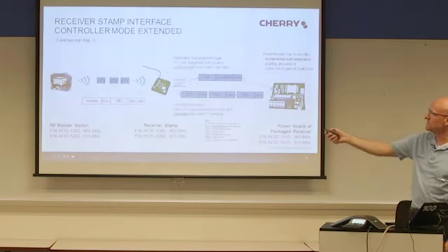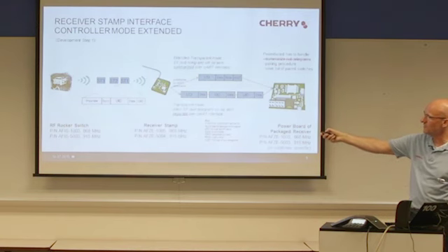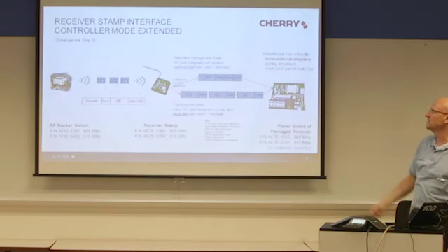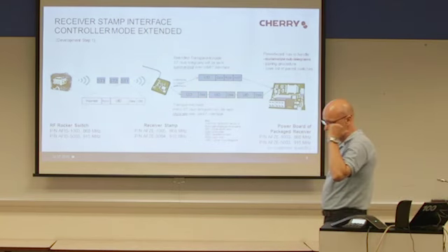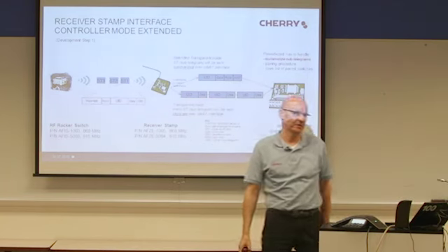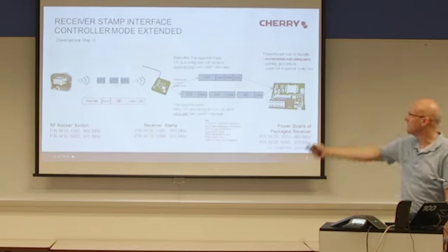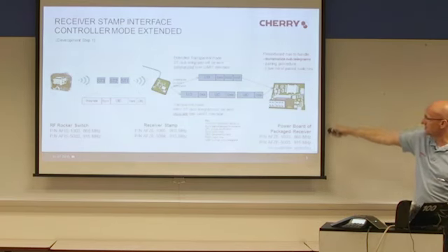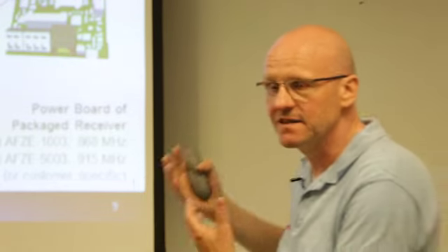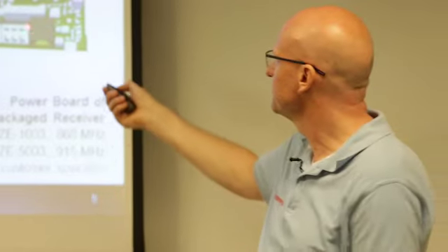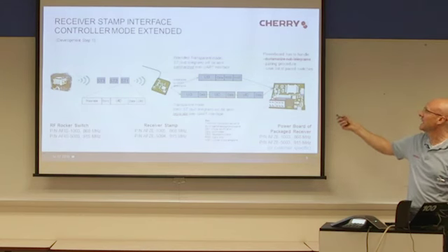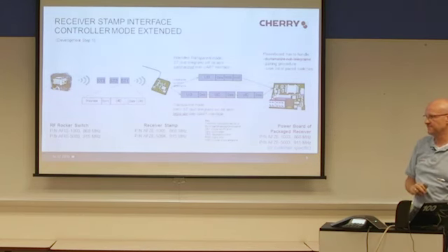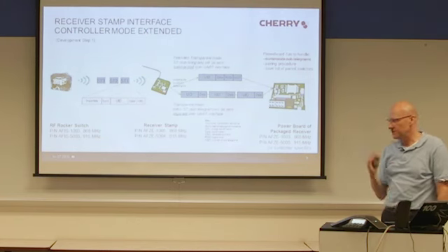In the next step, we summarize it on the RF stamp, and the power board gets only one message: switch 17 is pressed. But the power board has to save the list of paired switches. Then it can decide, is switch 17 important for me or not? And it has to handle all the pairing procedure. This would be the first development step.